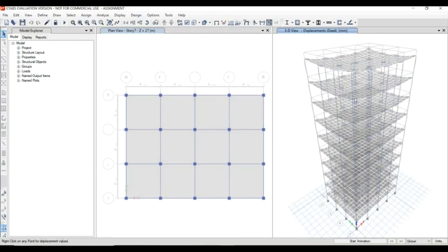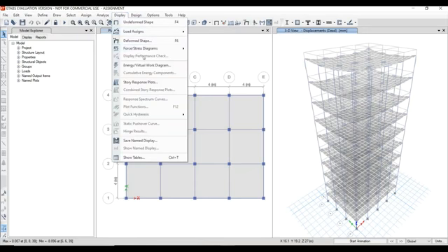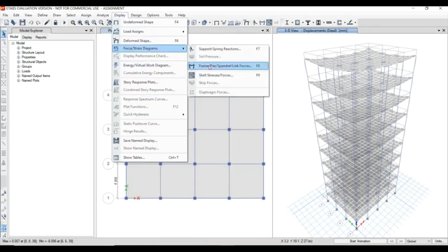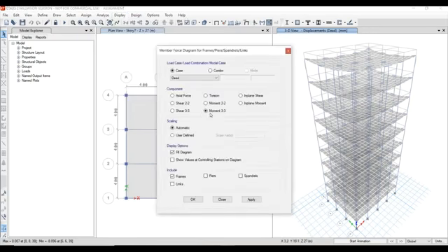In 3D view, you can see the deformations of every story, as displacements will be shown after analysis. So if you want moments and all other things of that frame section, go for display, diagram, frame, and if you want moment in 3 direction, click apply.